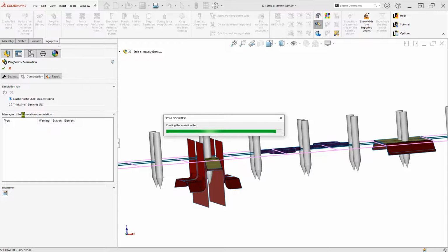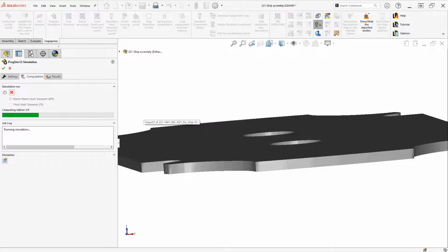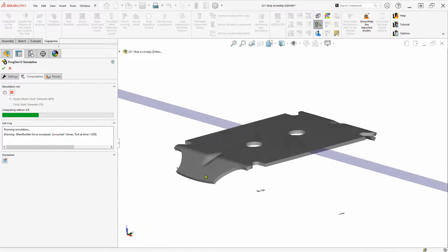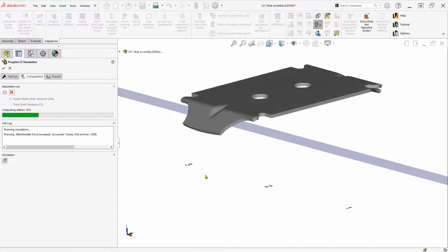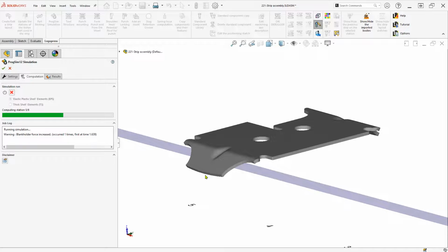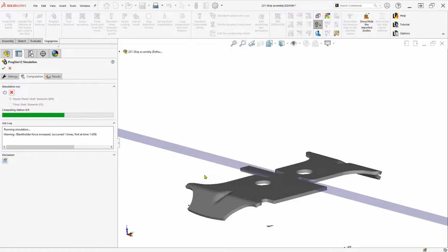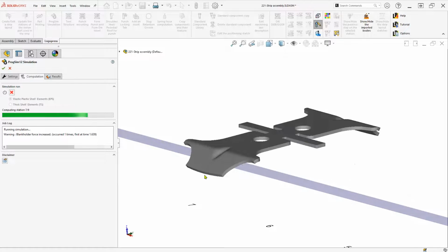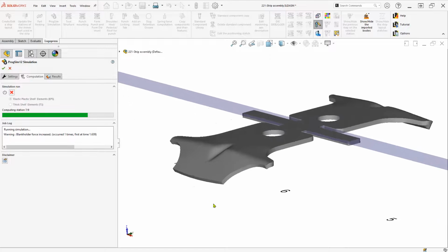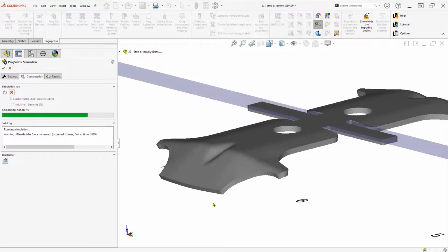And this is basically taking all of the surfaces that we selected and all of the parameters that we fed them and exporting that all out to the AutoForm incremental solver. This is the same solver that runs in the higher end software, but with just the various limitations that are applied to ProgSim here. So it's running the same simulation, but it's helping you extract that from SolidWorks here and feed it into the AutoForm solver.